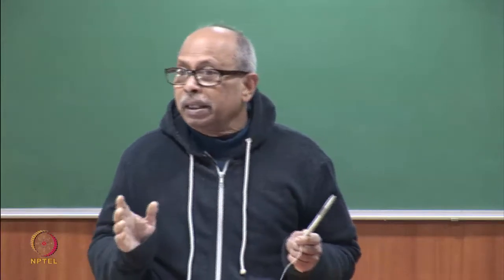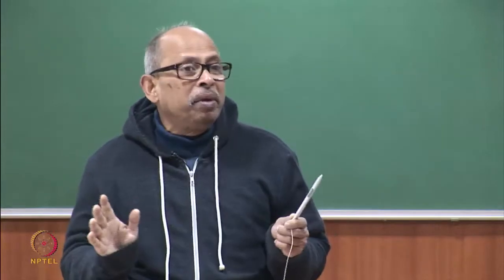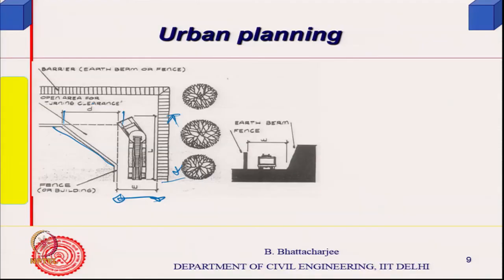You can expect that during an emergency they are not likely to reverse and go around. This is very difficult, even impossible, because it is an emergency. So, street planning should have adequate width and adequate turning distances, and the National Building Code gives you those values. The values of W and D for various L's, literature also gives you.